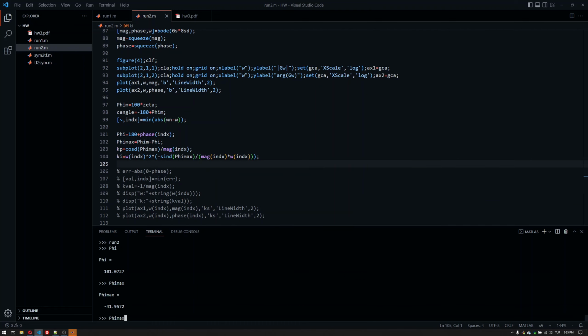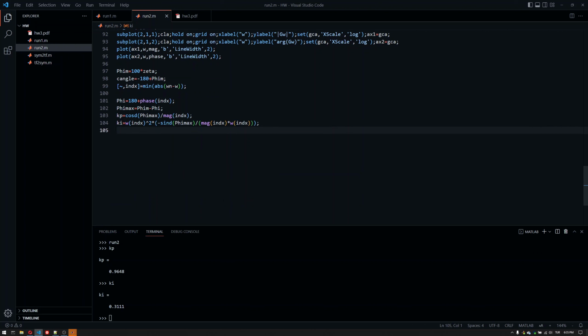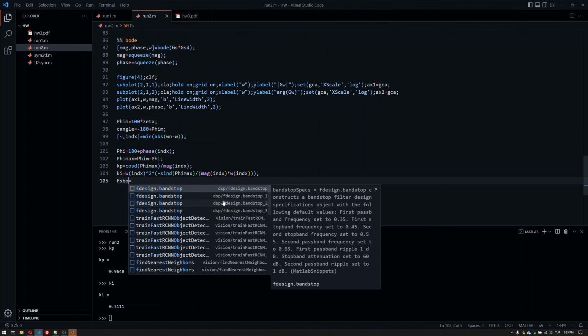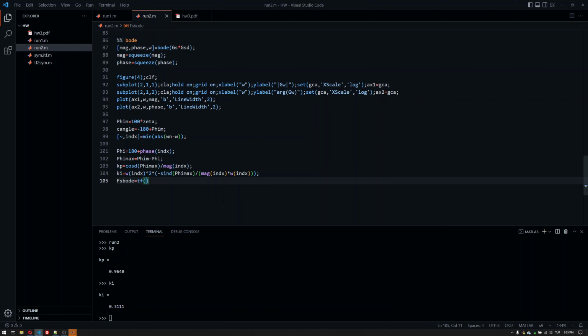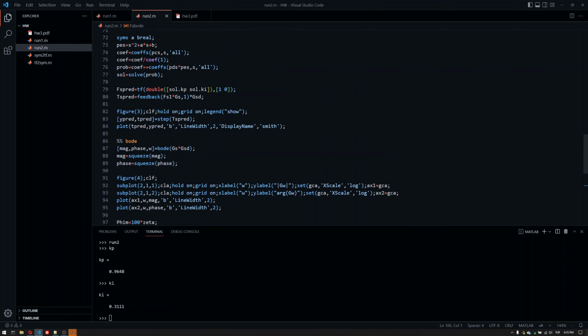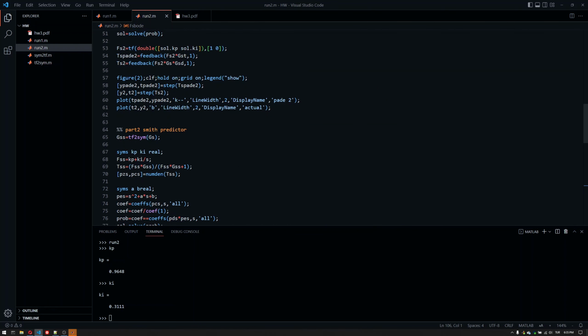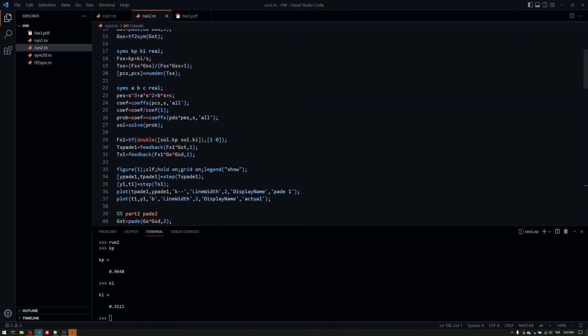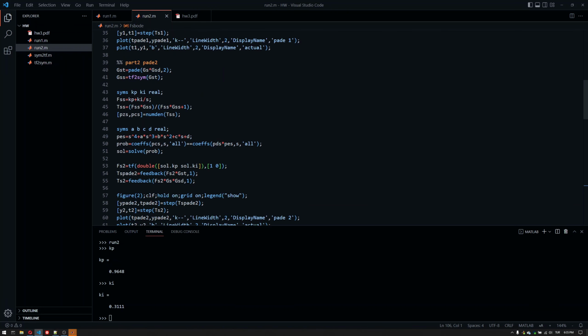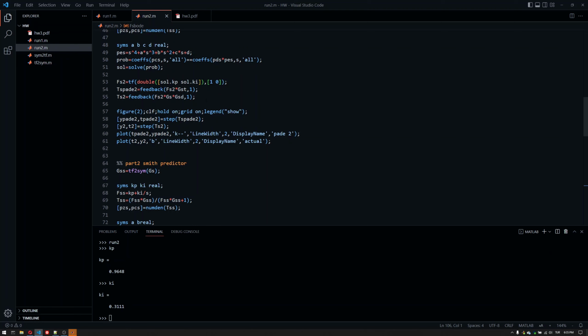So let's see if we messed up anything. So Kp, Ki. Let's define our controller. Let's call it body, tf, Kp, Ki, 1, 0. And then of course, let's have this feedback here and hold this thing here.